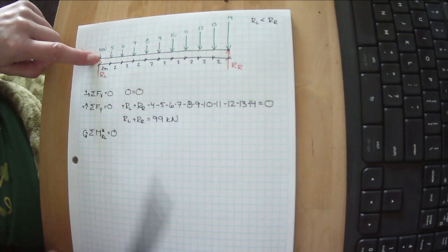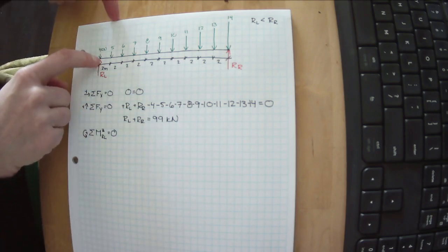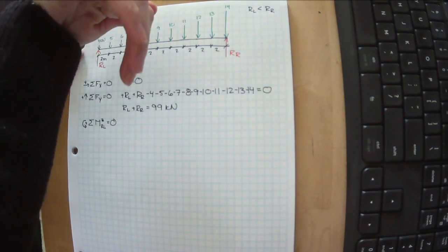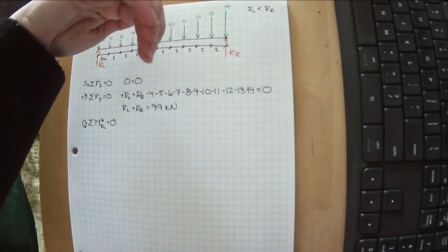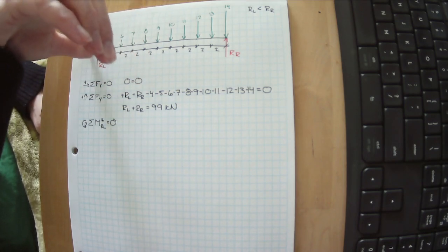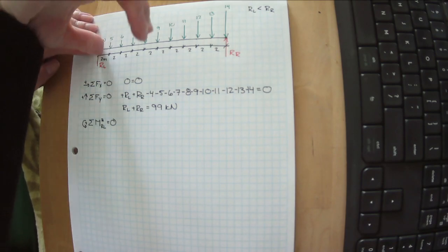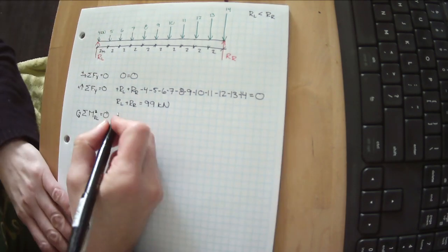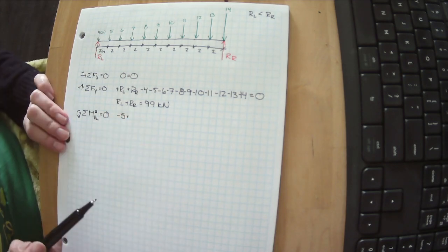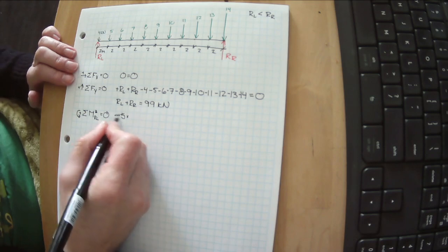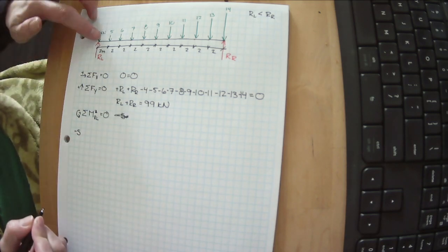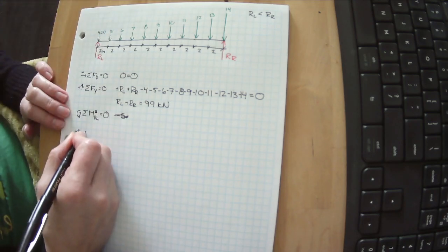Okay, let's come over here. Thumbtack, 5 kilonewtons, causes this to spin in this direction. I'm going to curl the fingers of my right hand in the direction it tries to spin it, and then my thumb will tell us what direction it's trying to spin it. It's in the negative direction. So we have minus 5 times, and to be a moment, you need a force and an eccentricity. In fact, I'm going to write this down here because I know this gets long. So minus 5 times its eccentricity is 2.